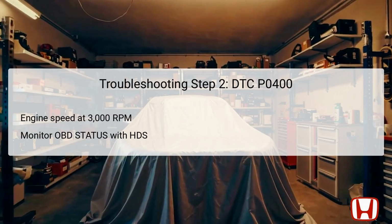The second step requires verifying the problem by starting the engine and holding the engine speed at 3,000 RPM without load.